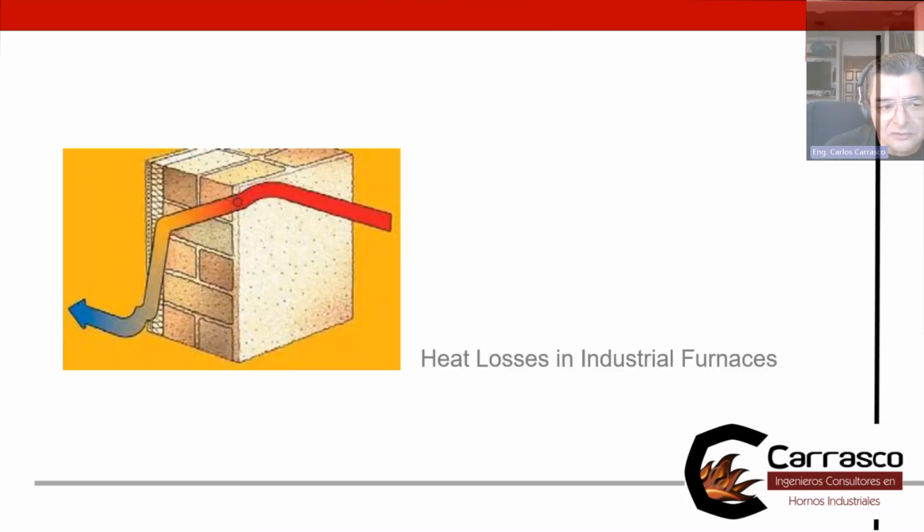In the furnaces, when we design the furnaces, I have these combinations of materials, properly selected, properly manufactured, the insulation materials to stand the heat on the hot face of the furnace, and also to make able to drop the temperature across the cross section of the insulation, to have a temperature safe for the operation, and also a good look for the ambient inside, outside the plant.